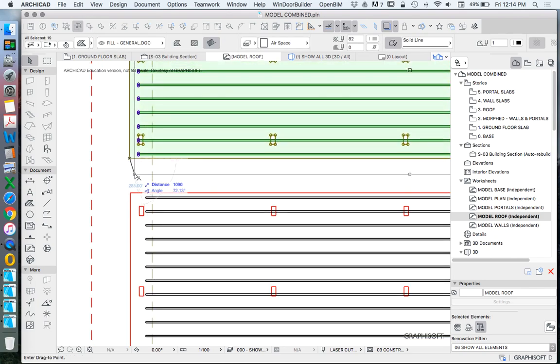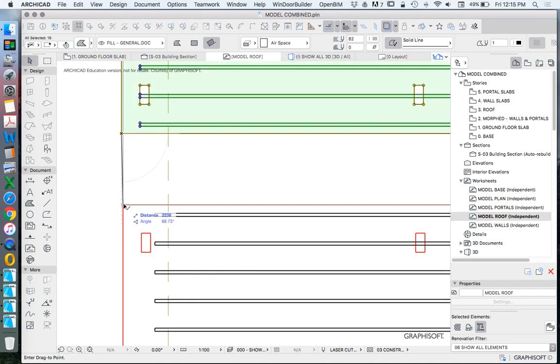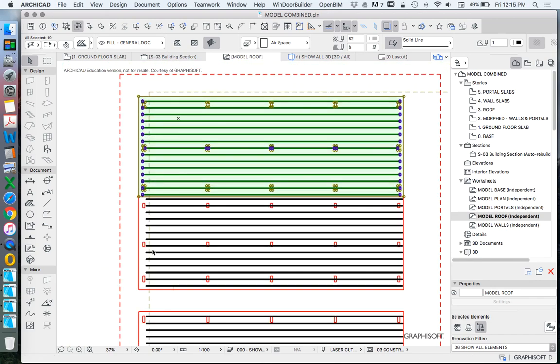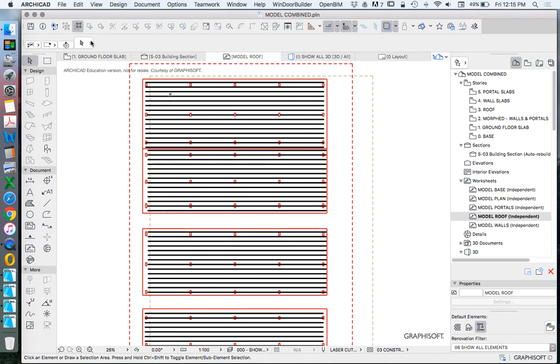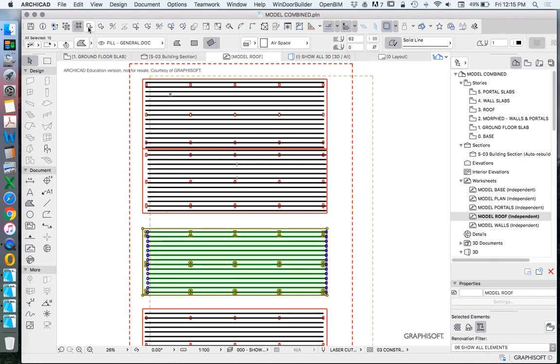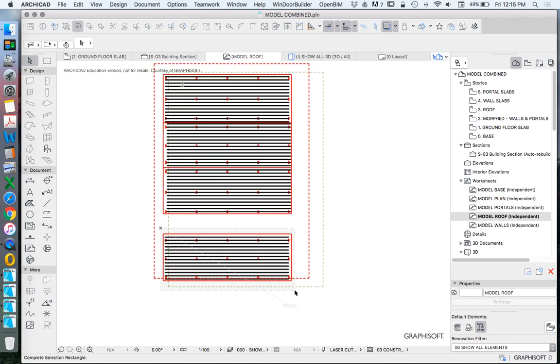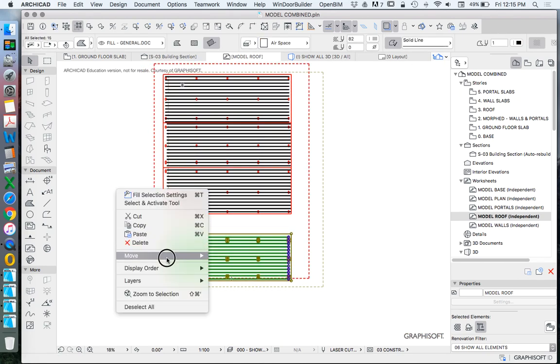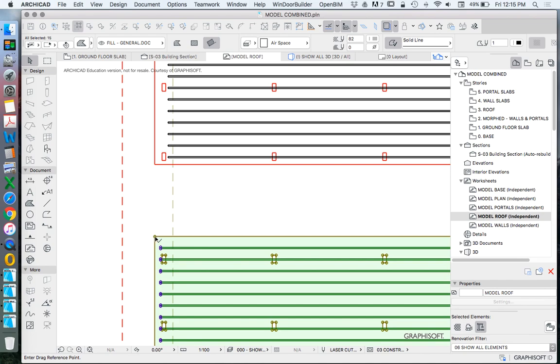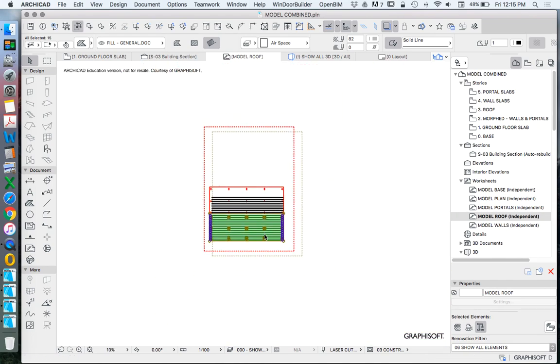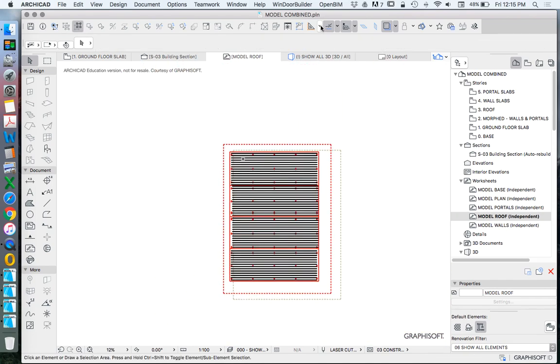Now if we want to get very, very fancy, the reality is we can join these together. We just need to then be thoughtful about the overlap in terms of what does that mean for pens, lines, because we're then using the laser cutter to cut the same place twice. What we should do is actually join them together and then use lines to separate it so we're not doubling up. But we'll keep it as fills for now, just to be nice and simple.